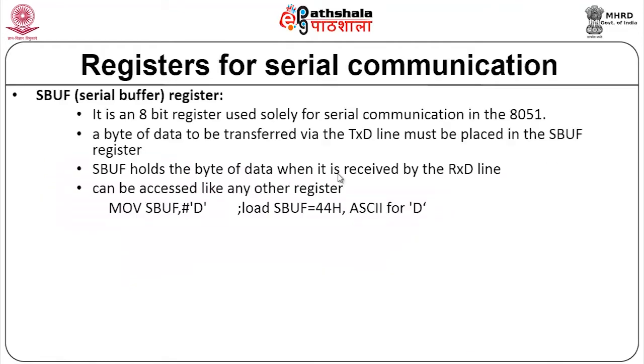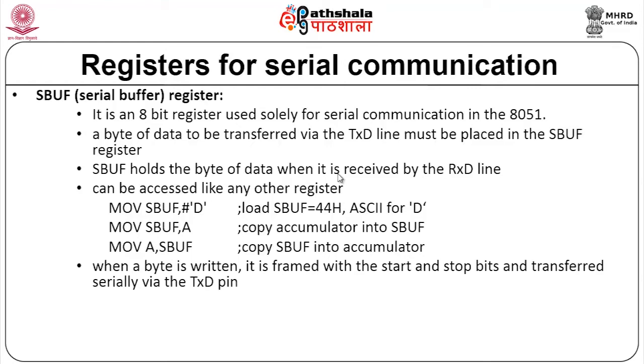And with your SBUF register, usually for serial communication, the first thing is whatever be the baud rate, we will be setting it. The second thing is how we will be sending the data. As I told you, if I want to send the data, it will be in a word format. If it is in a word, in the sense it is 8-bit. So if it is 8-bit, this has to be converted into bit after bit. That means it has to be serialized. So there should be an interface buffer which will be used for this particular purpose while sending it outside or receiving it from outside. So we will be using this SBUF register, which is otherwise called the serial buffer.